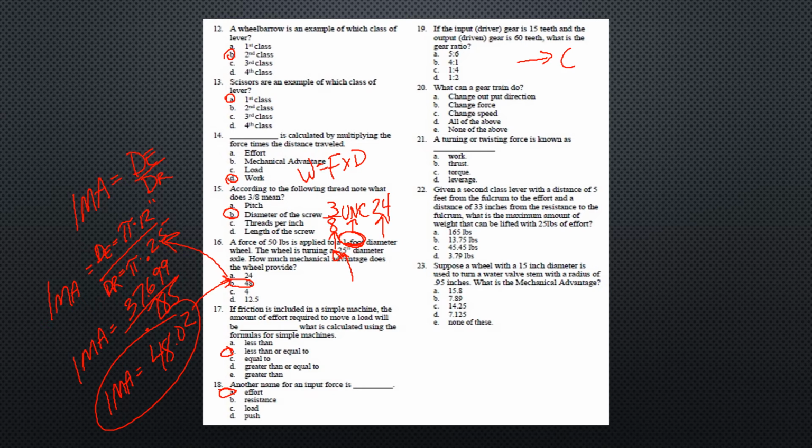So gear ratio should be on your formula sheet, is teeth out over teeth in. So in this case, my 60 is the gear that is being driven.